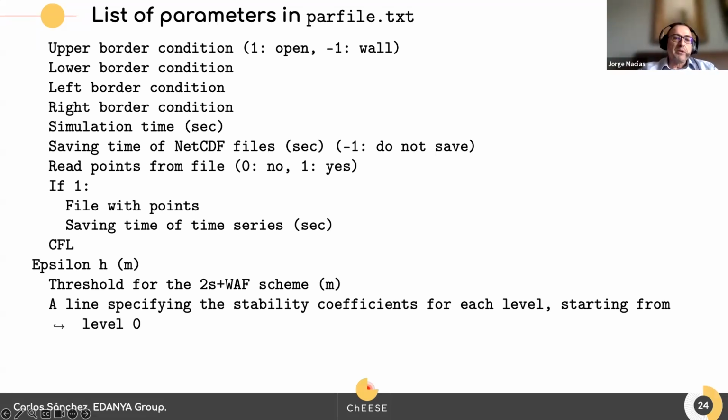No, I think we can leave it like that. Just to say that the standard CFL is 0.5, and if we increase it, the scheme could become unstable, but it may not. At the same time, the larger it is, the faster you move in time, so it has an advantage and a disadvantage. But it's something you gain with experience.